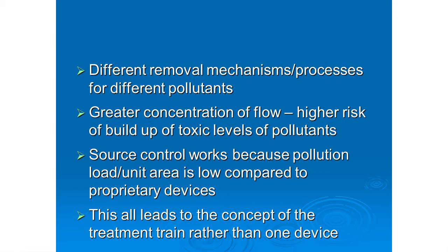We've talked about that, different removal mechanisms and processes. If you concentrate flow from a big area into a very small area, which is what we tend to do with normal drainage systems, then there's obviously a greater risk of the pollution building up to toxic levels. And there's certainly a greater risk of things not working.